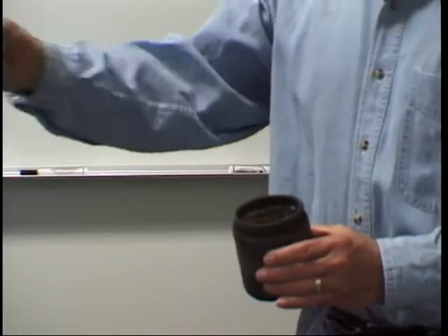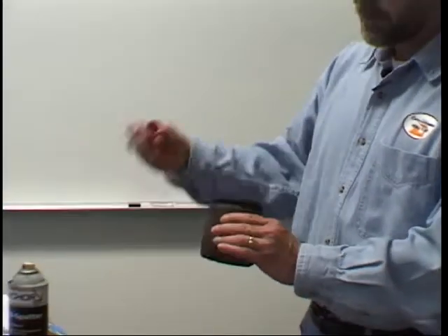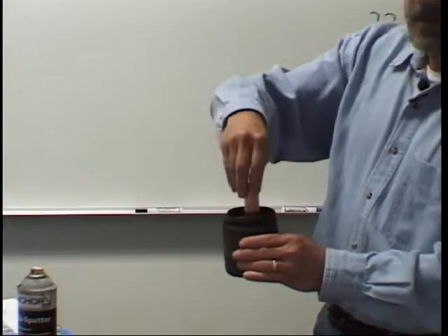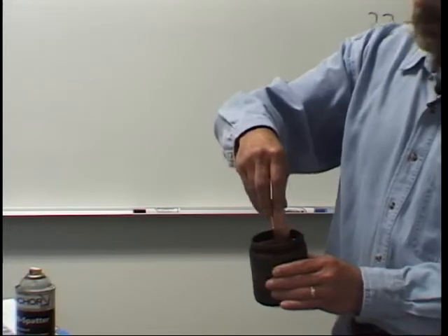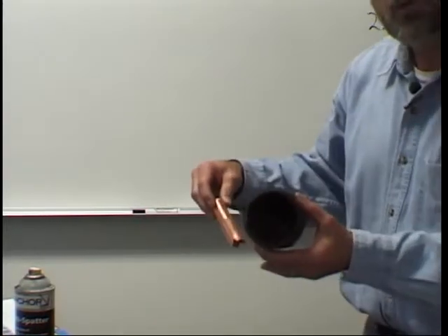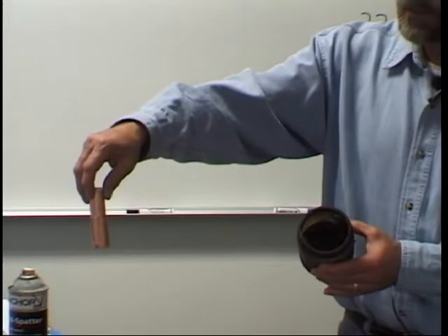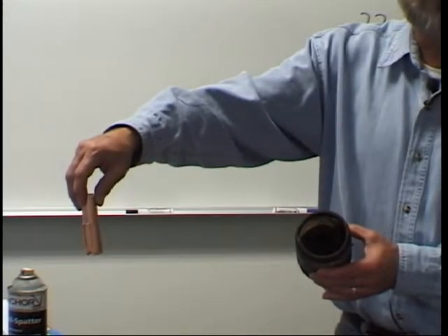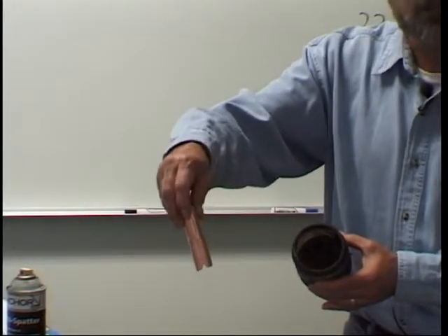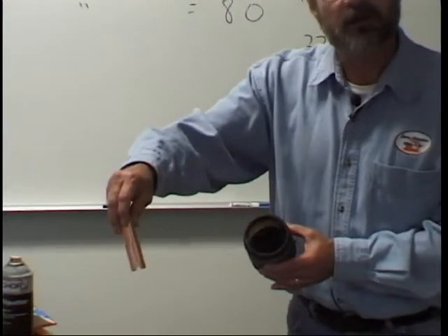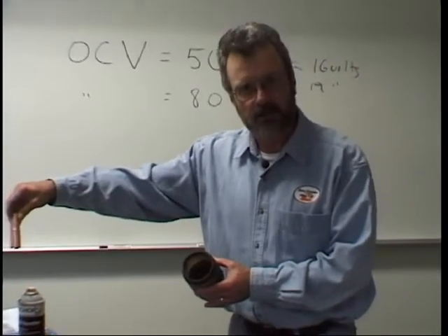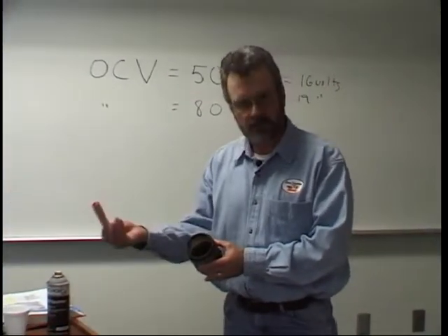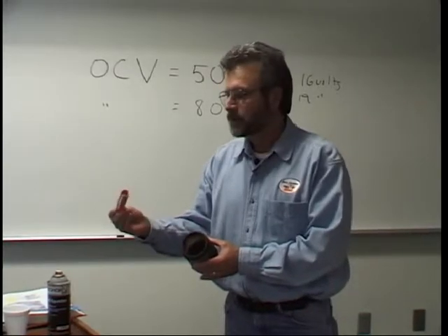And you'll take your hot gun, you've just cleaned it up, and you'll actually dip it in here and coat it. Now that stuff comes out pretty gooey and pretty thick, so you want to let it drip off, let the excess run out, and then get over on a piece of scrap steel and run a little bit before you start your welding again. And that also is another way of protecting the cup from spatter.